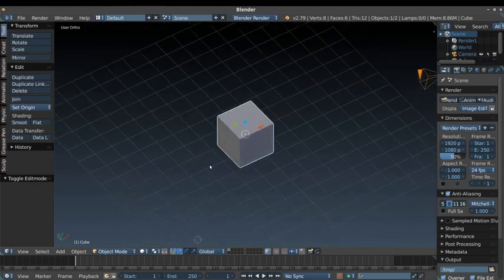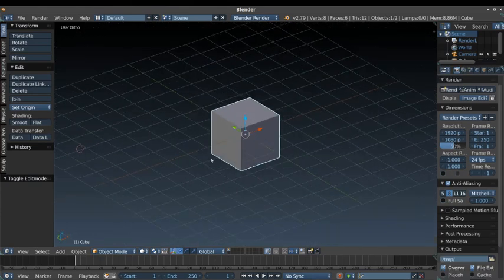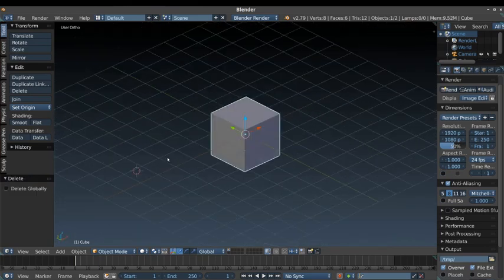Now we come to the meshes, the so-called 3D objects in Blender. The cube is a mesh. We can create multiple meshes. Another important part is the 3D cursor. The 3D cursor is a freely definable reference point. To set the 3D cursor, simply press the left mouse button. If we now create a new mesh, it will always be positioned on the 3D cursor.